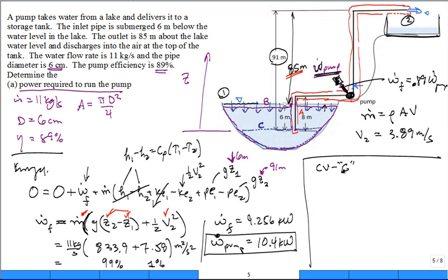Yes, sir. So I just remember for Cal 2, if the level of the lake is dropping, the pump has to work harder to move the liquid. Does this... if Z2 minus Z1, so if Z1 goes down, then it becomes closer. Instead of 85 meters, it may go all the way to 91 meters, where you have to pump it up 91 instead of 85. So it's going to take more energy.